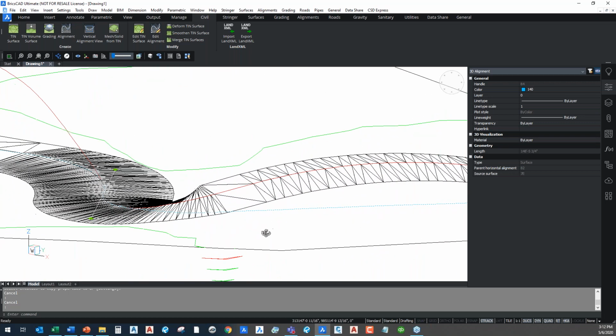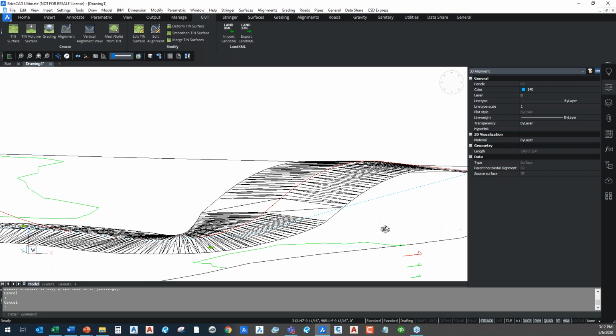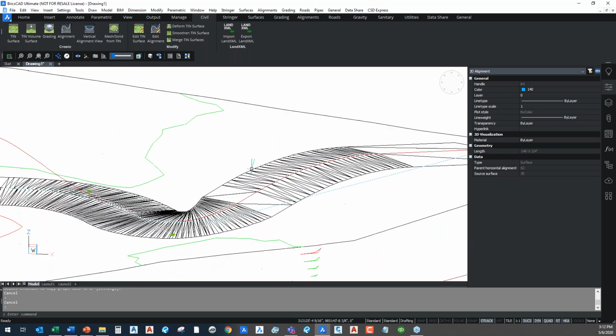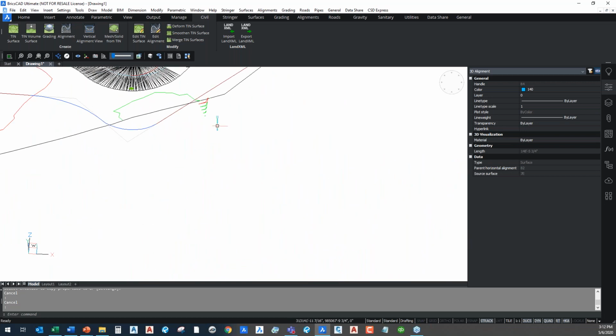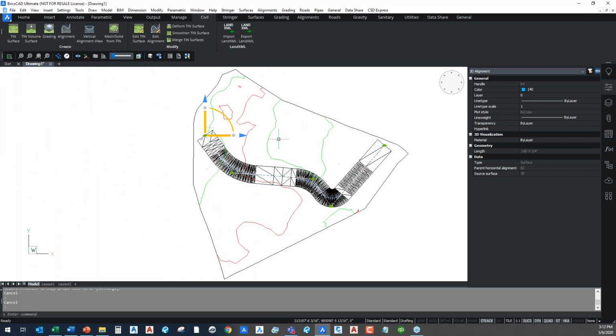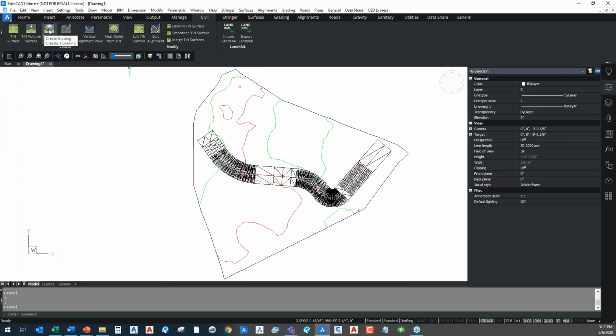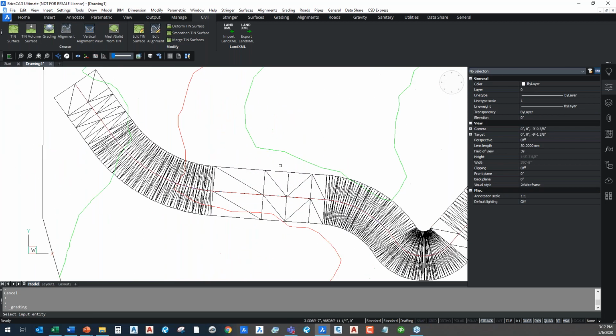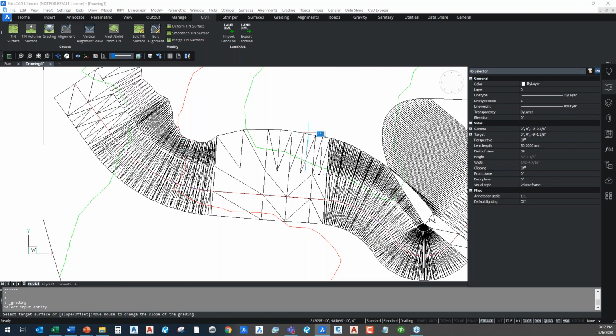to actually go up and pull up my road, change the slopes, the conditions to whatever I need them to be. And then from there, I can go in and, using the same grading tools we used before, go from the edges of the existing contours here and say, again, I want to go from this point. You see I can just select the target surface. I want to daylight down to the surface. And you see I can just stretch out.